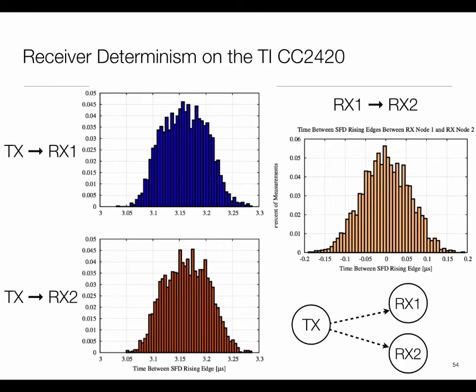And you would see this with the other one, and the final thing is receiver 1 to receiver 2, another one. So there's a variation, and no pair are identical either. They're roughly similar but not exactly the same, so there's always some gap or other. The difference between these two is what is shown out there. Again, a major spread. So what it says is that this is the bottleneck in terms of how accurate you can time sync. You need a more deterministic communication medium and communication chips to make this happen.